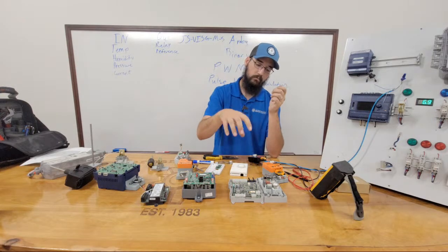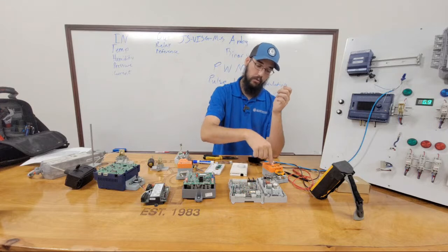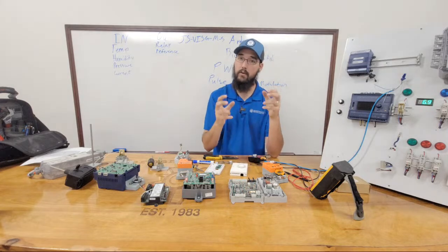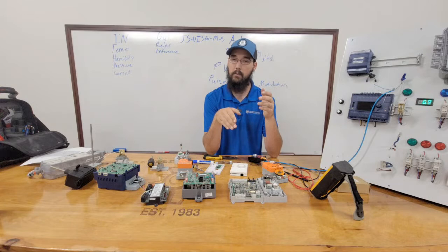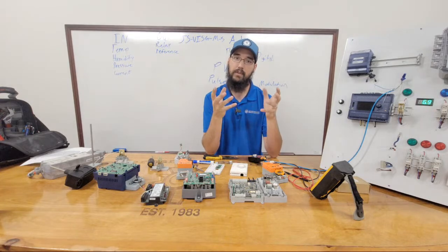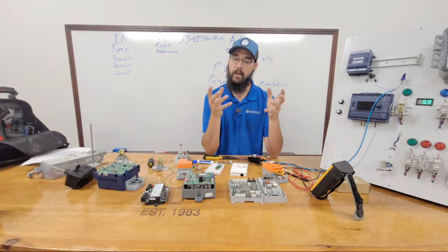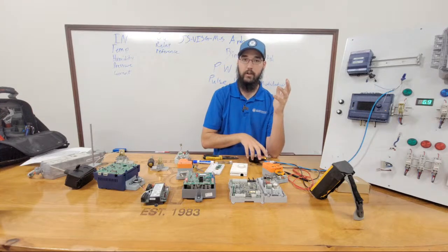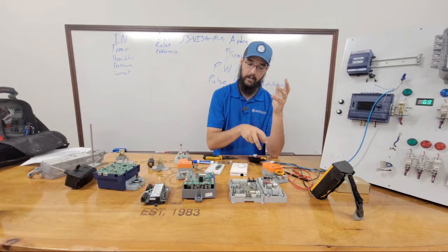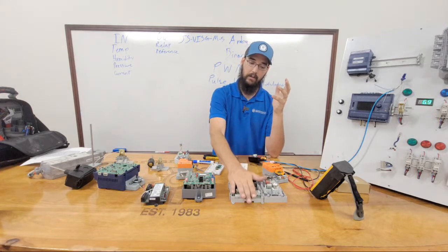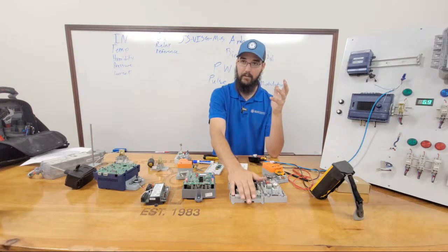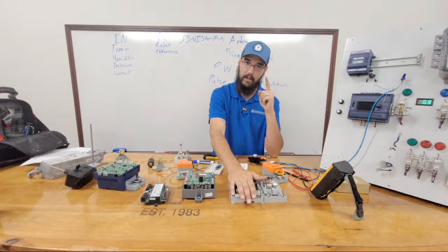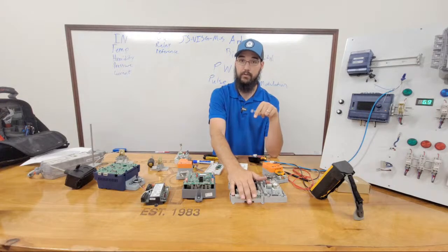Right? But when you remove that off of whatever that load is that's overloading that output, now all of a sudden you see the voltage. So if your signal generator can hook up to it and modulate it, but the building controller can't, then it is very likely that it is actually the building controller.